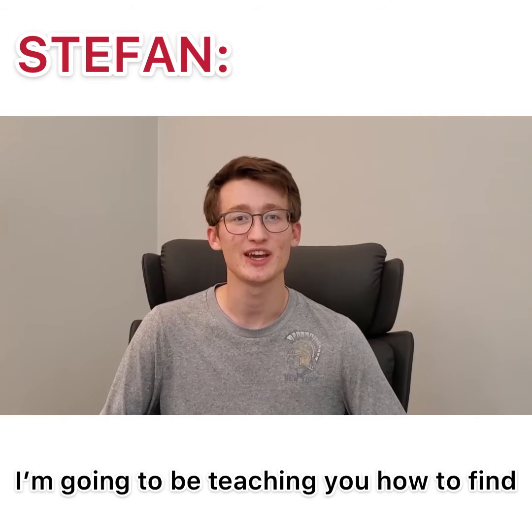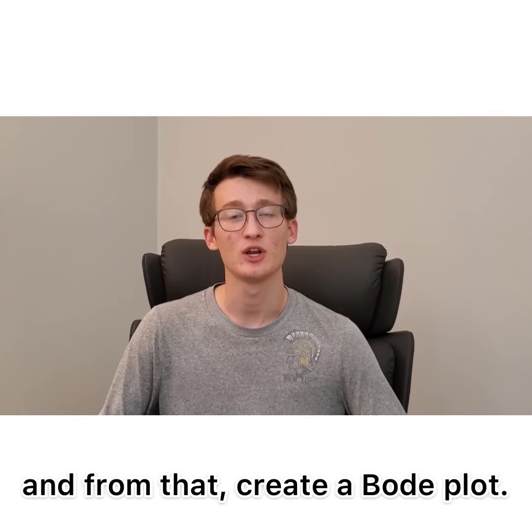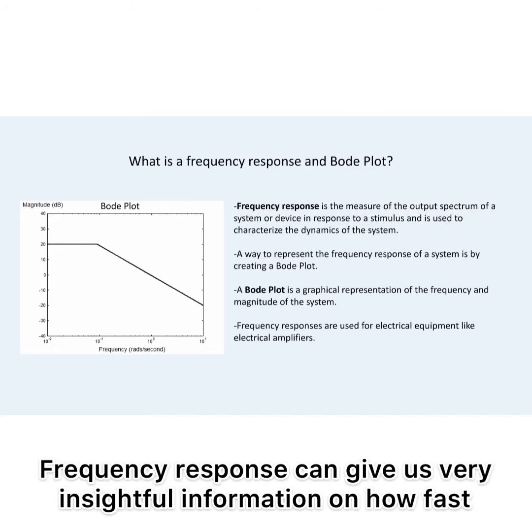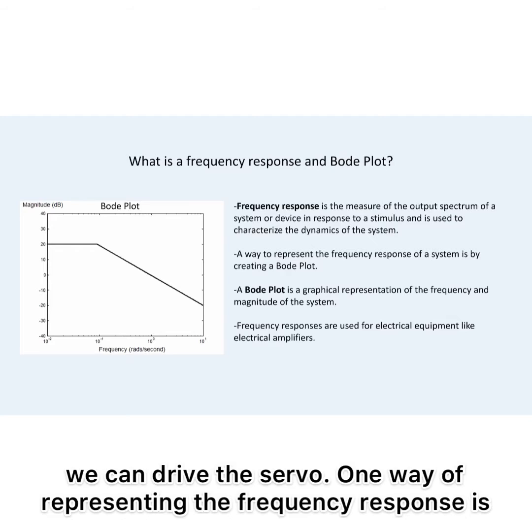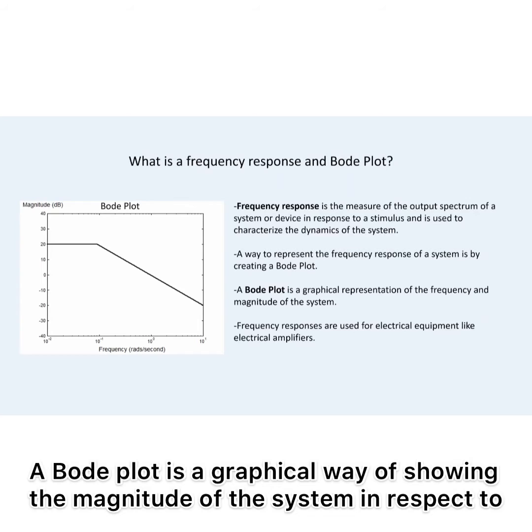I'm going to be teaching you how to find the frequency response of a servo, and from that, create a bode plot. Frequency response can give us very insightful information on how fast we can drive the servo. One way of representing the frequency response is by creating a bode plot. A bode plot is a graphical way of showing the magnitude of the system in respect to the frequency.